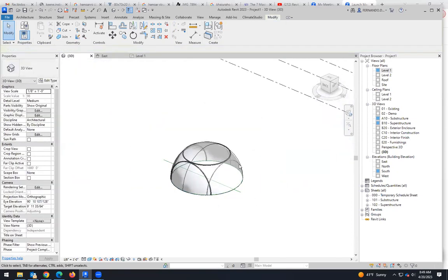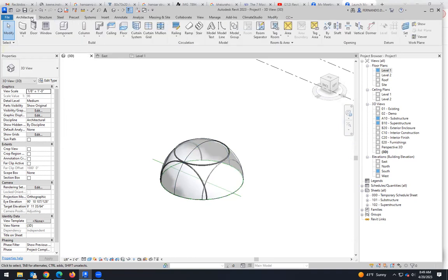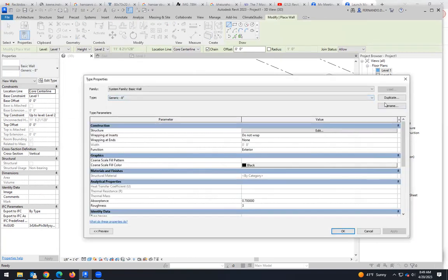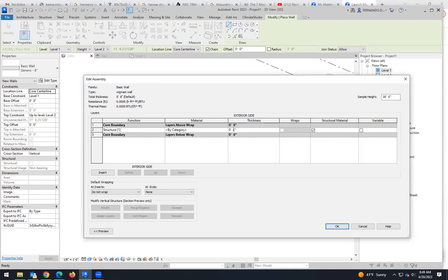The thing is that if I have this mass now, and if I go to, is this a wall or a roof? No, let's say that I'm going to create a new wall, okay, architectural wall, and I edit type, I duplicate, and this is the Wigwam. Edit, and now I can select here something very thin, like 1/8 of an inch.